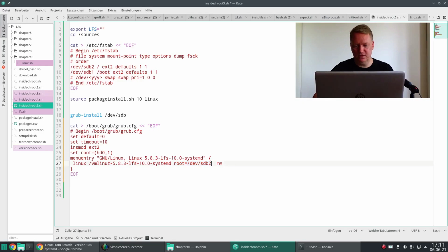And then the kernel just gives up too fast. It says, is there an SDB2? No? Okay. Then you get a kernel panic because the answer of the device is too slow. Because of that, I will put a root delay 10 here and a root wait also.